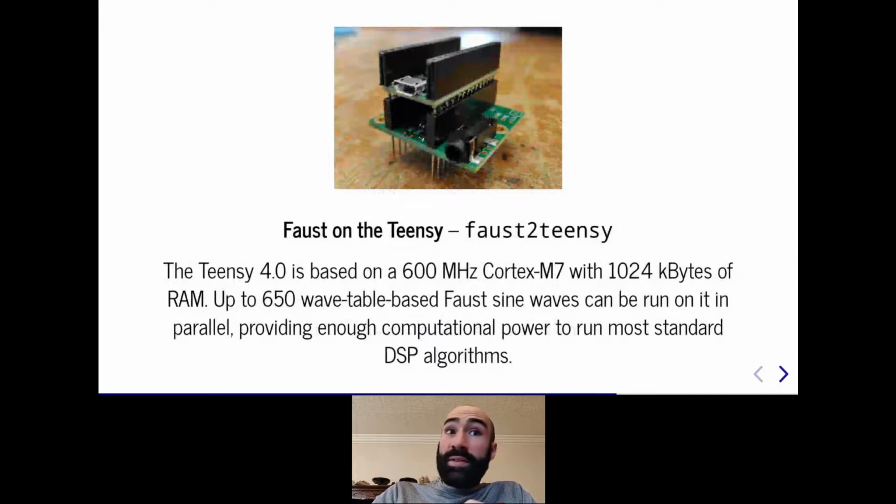Just like the OWL, Teensys are based on an ARM Cortex-M microcontroller, which in some cases, like for the Teensy 3.6 and the Teensy 4.0, host an FPU, ensuring compatibility with Faust. Once again, we can only generate floating point C++ code with Faust.